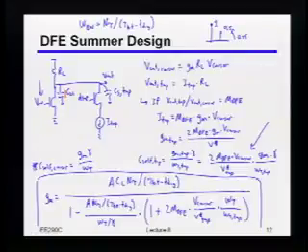And so notice the same thing sort of happens with the DFE because the amount of current you have to use in that DFE is also proportional to the GM you had on the input device in the first place. Right? In other words, what the DFE is really doing to you is it looks a lot like just a differential amplifier or a standard common source amplifier, except that now the actual intrinsic bandwidth you can get is degraded by the amount of correction that you have to do.